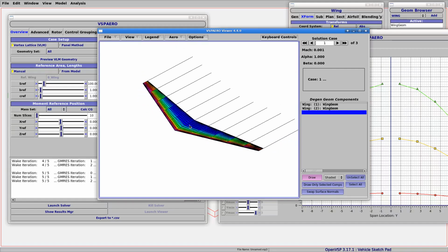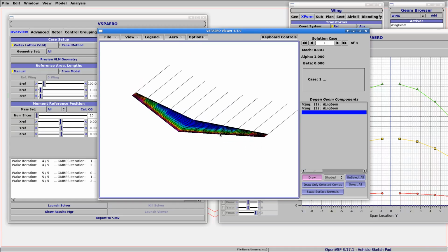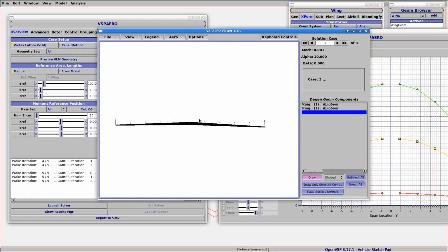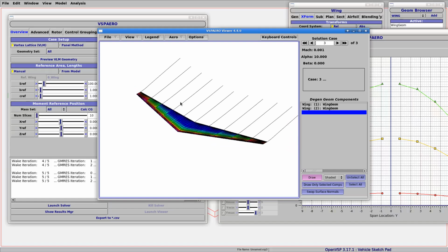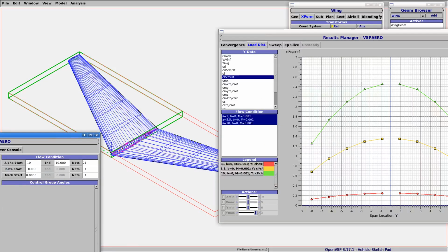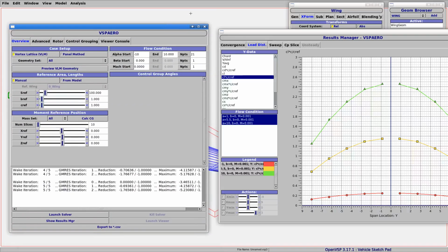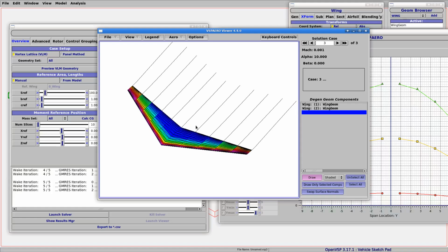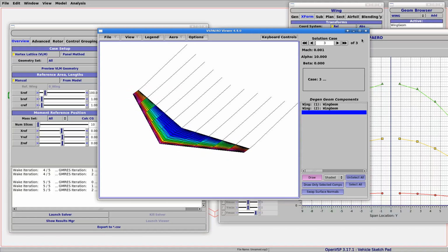It's really boring here because we don't have many points along the wing, and also, we can change the angle of attack here to angle of attack of 10, so you can see that the air is flowing at a different angle there. At the wingtips, you can see that the wingtip one is going up a little bit, so there's a sort of beginning of tip vortices, but there's not much resolution in this simulation. As I mentioned in the previous video, the more sections you have along your wing of these explicitly defined tessellations or divisions, the more time it's going to take and the more detail you'll see in this. But as I also mentioned in the previous video, don't bother increasing that too much until you get right to the end of your design cycle, I'd say. It doesn't really help much, it just slows things down.